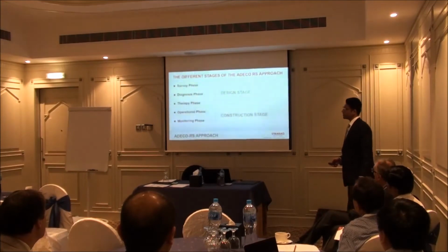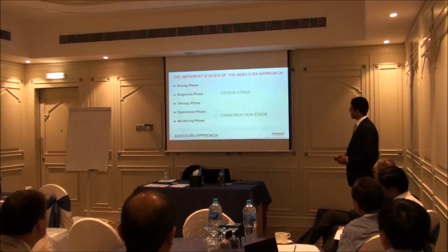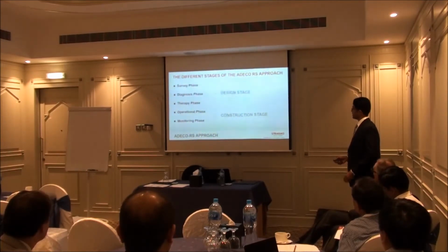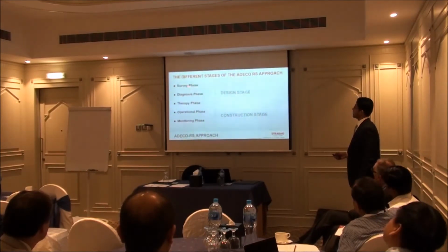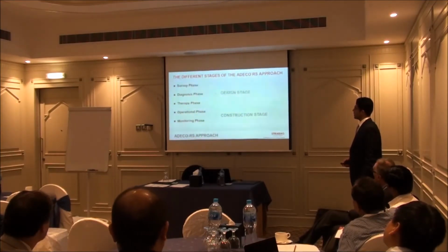So what are the different stages of the ADECO-RS approach? ADECO-RS differentiates between design stage and construction stage. The design stage consists of these phases: survey phase, diagnosis phase, and therapy phase, and the construction stage consists of operational phase and monitoring phase.